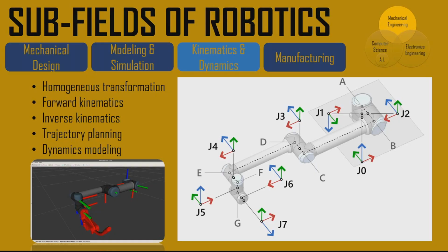And then another thing would be inverse kinematics, which is the opposite of forward kinematics, as the name says. Inverse kinematics deals with finding the joint angles of the robotic manipulator arm given the end effector position. So this is the opposite scenario. And then of course, for a particular problem, a trajectory or a path of a particular robotic system, a robotic arm, needs to be defined, and that is done also using kinematics and dynamics by a concept called trajectory planning.